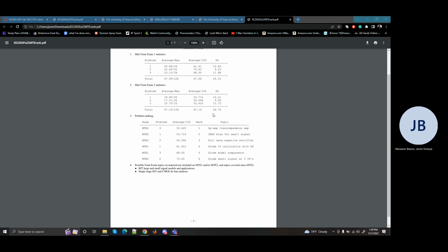So then you can do the small signal analysis. You can look at inputs and outputs, and you get your actual gain of your AC signal. The reason that you want to do it at the small signal is because Thevenin's only works with linear devices. BJT, exponential, it's not linear.